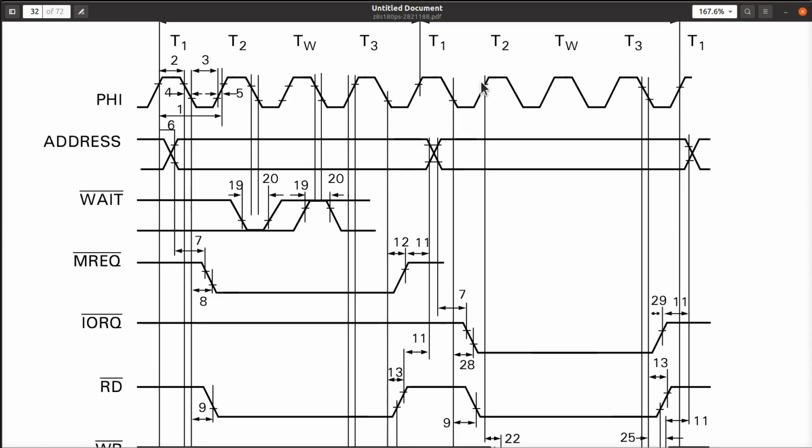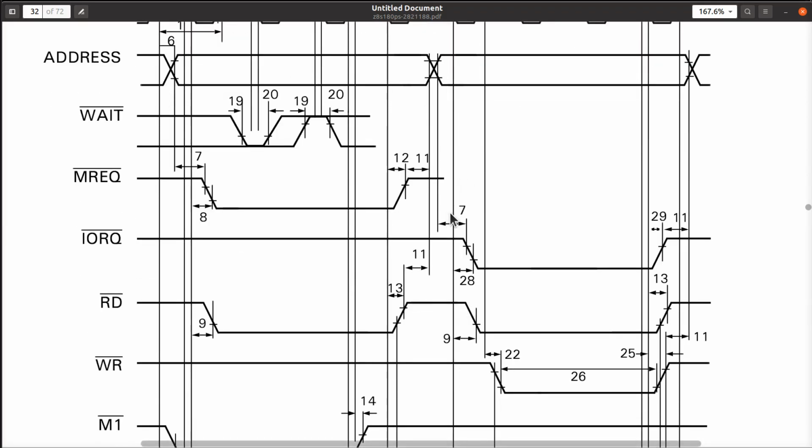So the latest that you could see the address would be 5 nano before this rises, which is actually 40 nano after this. That's outrageous compared to the time here where it says 30, which also felt outrageous to me. Now, I don't ever expect to see it hit the worst case, but I want to model it to make sure that what I'm doing, and I want to count on it, will still work even if we get the worst case values.